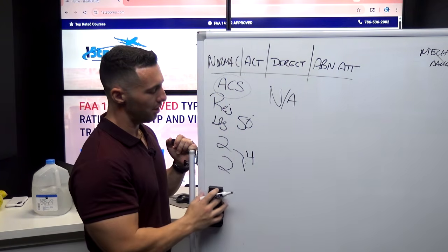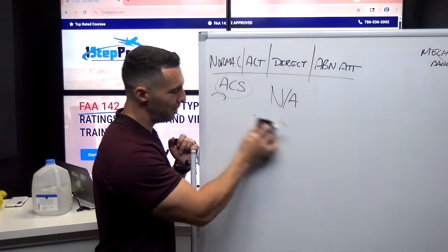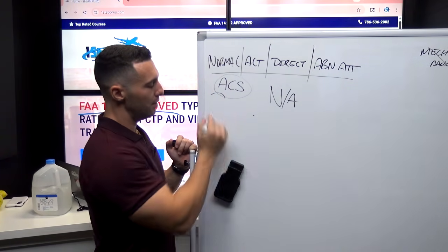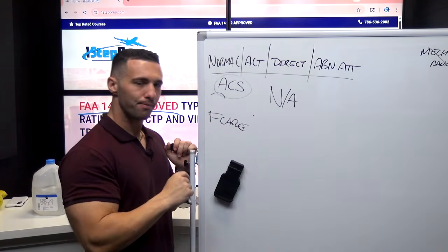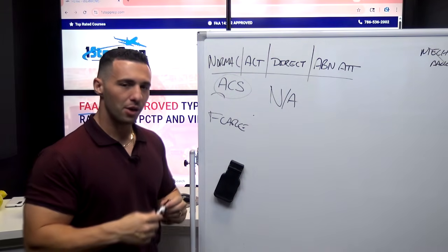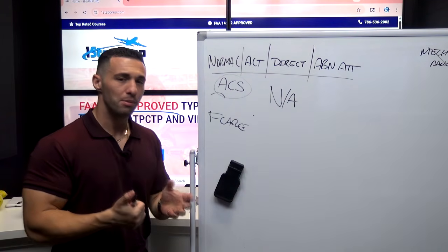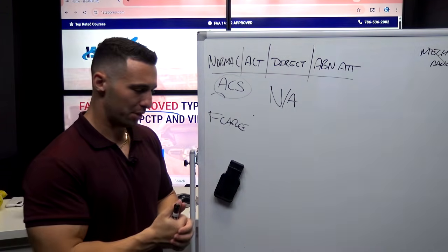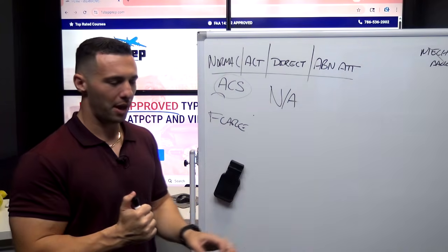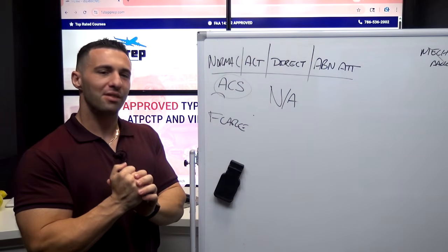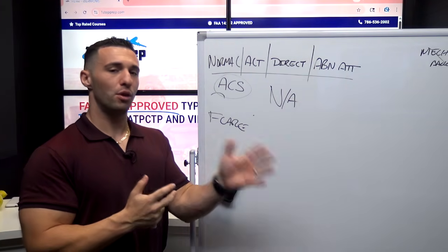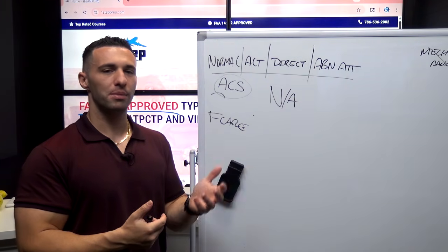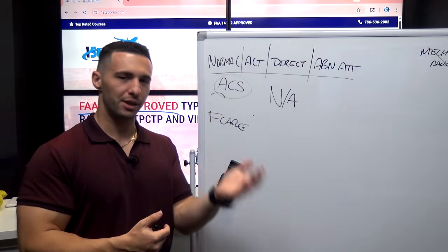That's reason number 1. But reason number 2 now is because of the flare mode. Remember, the flare mode is applying this nose-down pitching moment. And when the jet is applying the nose-down pitching moment, and all of a sudden we do go-around flaps, it's a lot of aft stick input that's required to not only A, bring the nose up because you're going around, but B, overcome the natural flare mode, bringing the nose down.